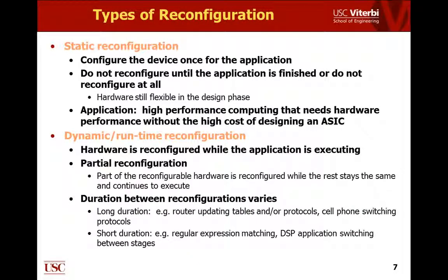There are many ways of doing reconfiguration. One is called static reconfiguration. That means you get all the configuration you want on the device statically at design time before the operation starts, and then you don't change the configurations at all. A lot of the FPGA applications are in this space where you configure the device once and repeatedly make use of it without having to change those configurations as the computation proceeds.